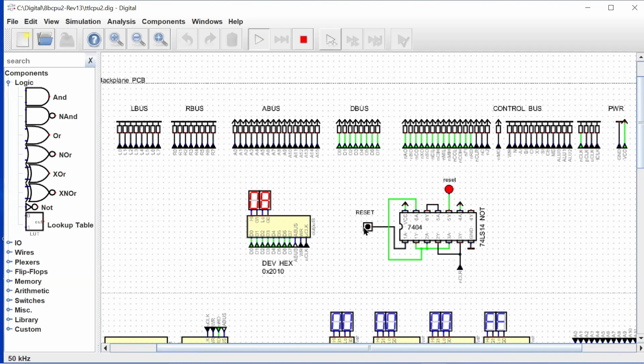So we've just powered it on. Our RC circuit here starts at low, and we're in the reset condition. And then the 2 seconds goes by, and then this can run. And we see our reset LED goes off. Our not clear signal goes high. Our computer is running, and we can see that our cool hex digit TIL 311 display is working.